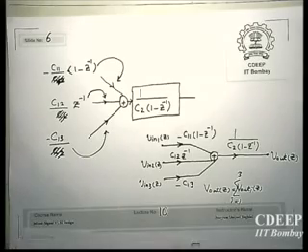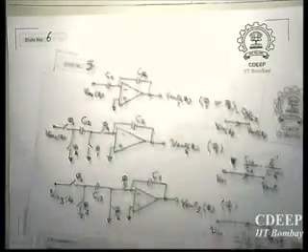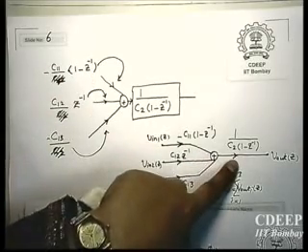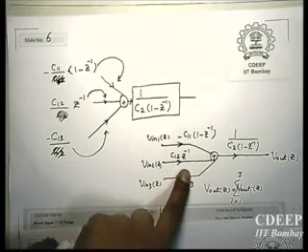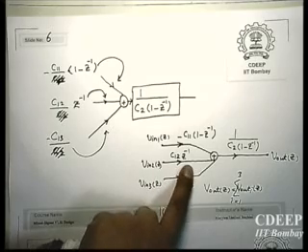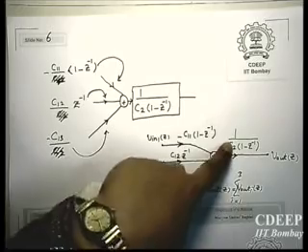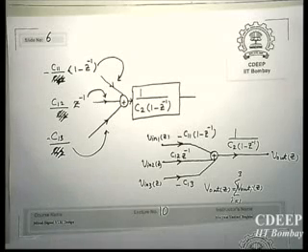I mean, the whole point is that when you see this architecture, you know that it corresponds to this transfer function. Eventually it means that this branch and then one integrator. If you see the second one, which is forward Euler, you know it's a multiplication by Z inverse, which is one delay and then integrator. And the third one doesn't have any delay, only C13 and then integrator. So 1 upon 1 minus Z inverse is integrator.